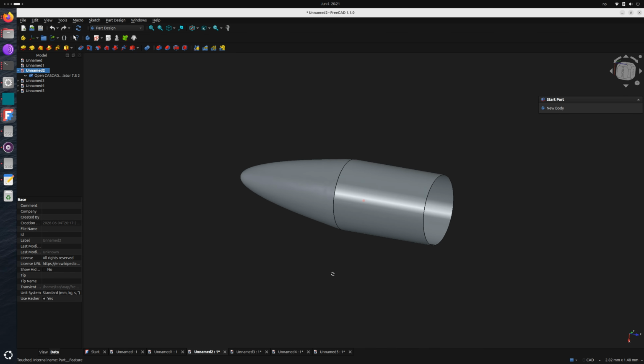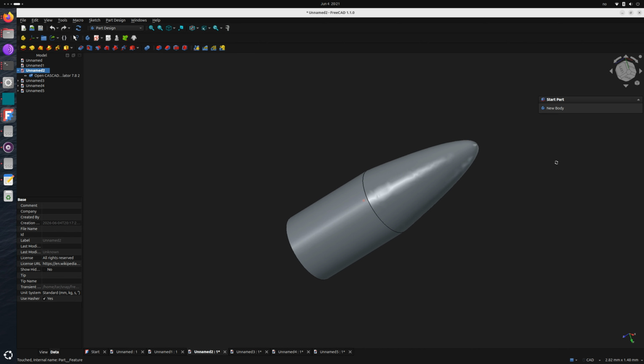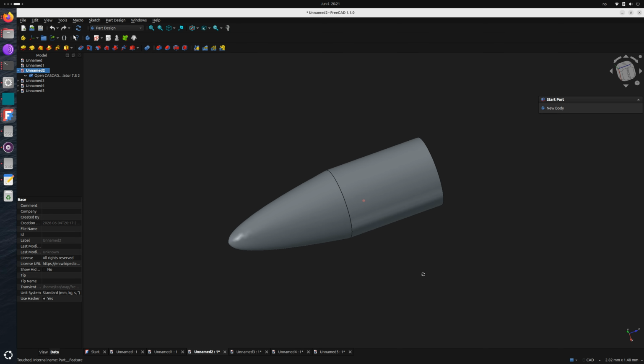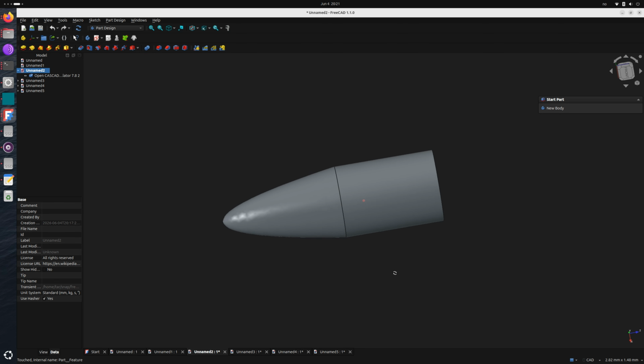Start with the hub, the central cylinder the blades bolt onto. Too small and there is no room for the pitch machinery inside of it. Too big and it blocks the water you came for. The rule of thumb is to put this roughly between 35 to 60% of the blade diameter.